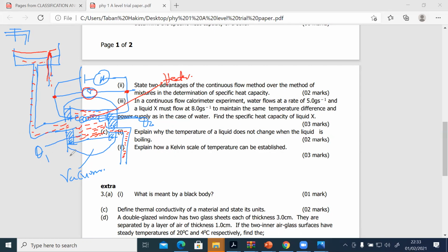Now, in this case, what is supplying the heat? It is the heater. So the heat supplied, IVT, is equal to the amount of heat absorbed by the water, which you can call mc change in temperature, plus the heat loss to the environment. We use capital H. Now, to talk about the rate of heat transfer, I'll simply divide everything by T. So the power supplied is equal to mc change in temperature plus h, where this h is the same as the capital H divided by this time T. So the capital H is the heat lost, and the small h is the rate.